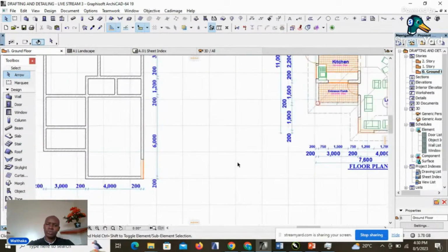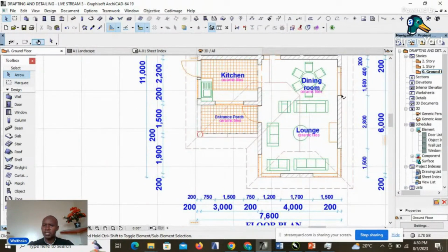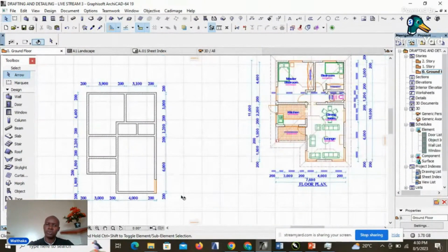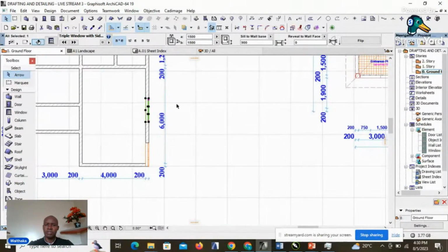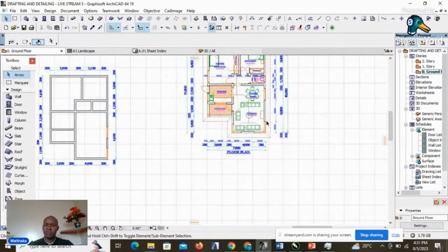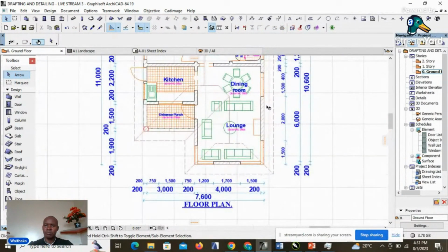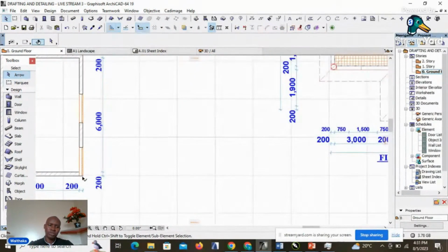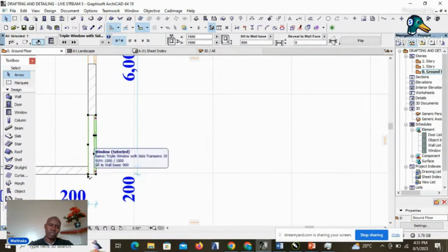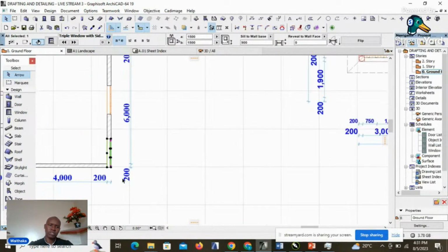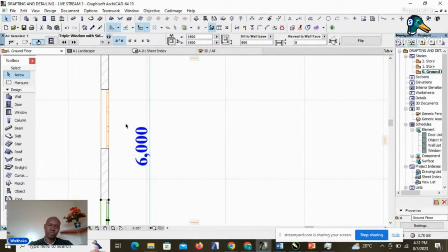Then we have another window. It is 2800 from this window. So what we will do is that we will just select this window. We drag a copy, Control Shift D, then we displace it at a distance of shift radius 2800, but you'll find that we did not achieve the exact distance, simply because I've used this point to reference to displace my window. I should have picked it from this point, and it should have given us 2800.